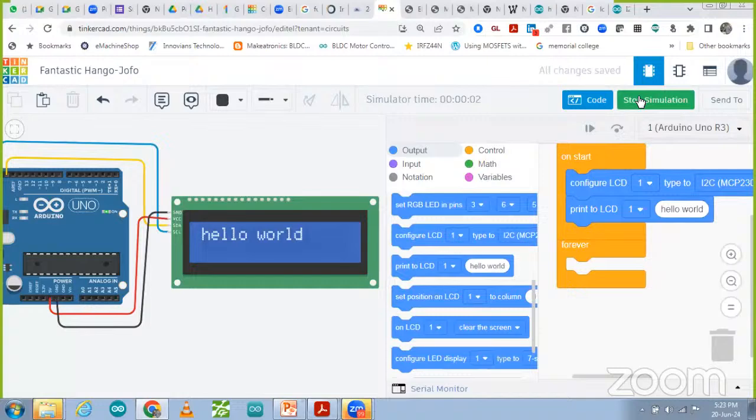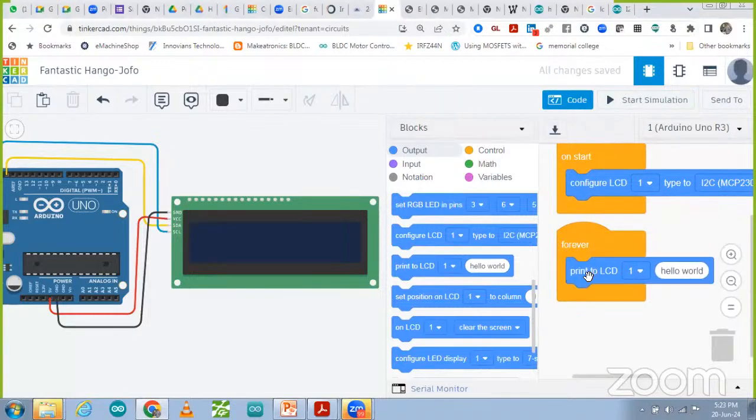So if you want to print any temperature value or any other sensor value, that also you can print on the LCD and you will be able to see it. This one is for 2 pins. So 2 pins you can use for signal wire, and 2 pins you can use over here for VCC and ground. And you can easily integrate an LCD, and you can use all other pins for other applications.